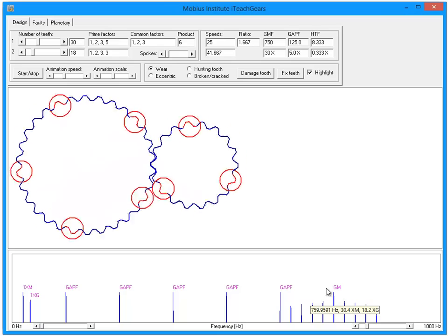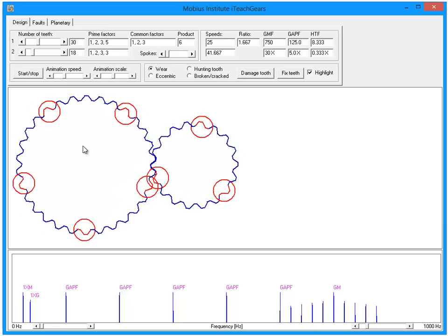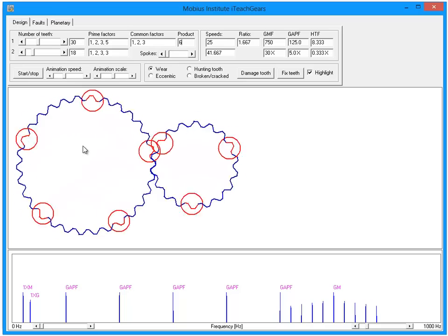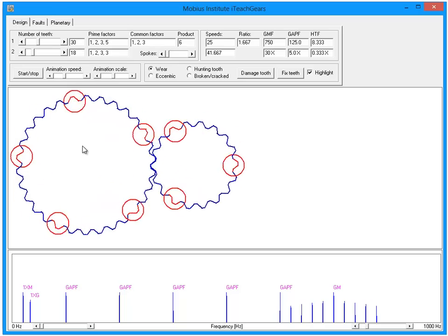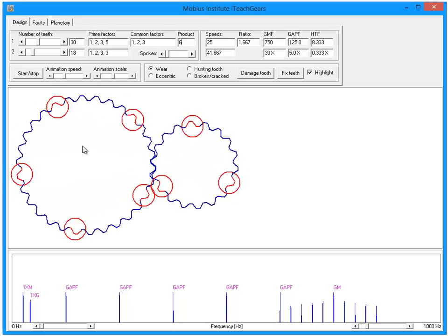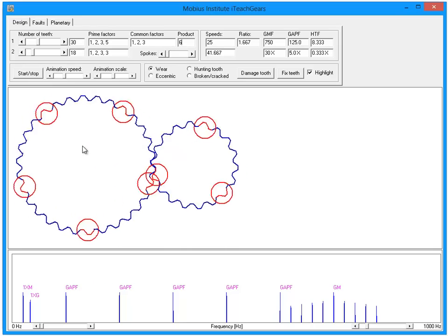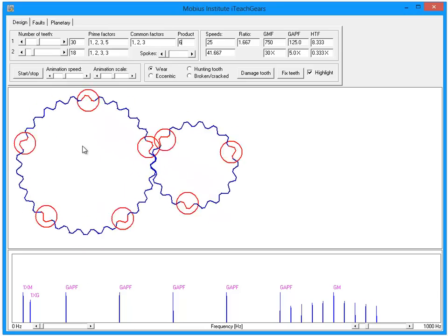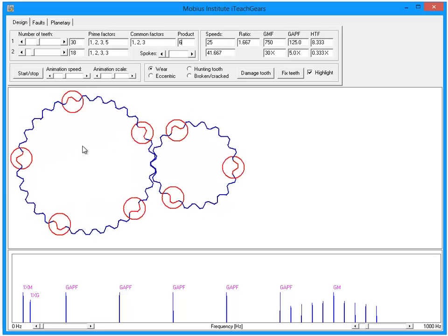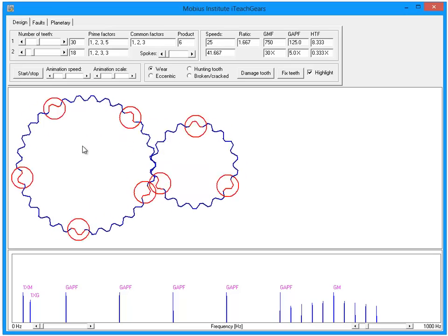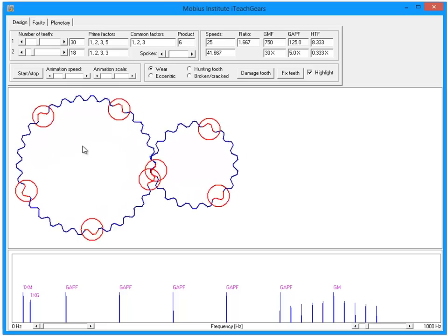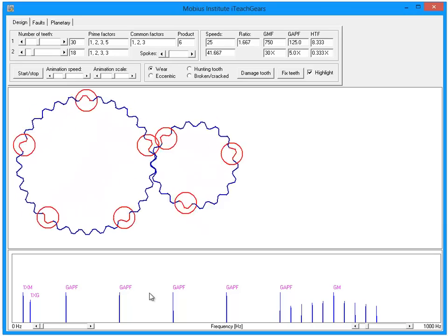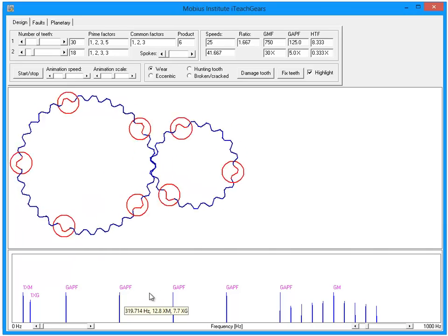And if you imagine taking this gear out of the gearbox, suspending it on some sort of cord and hitting it with a hammer, it's going to ring. It is a metal object. Now, when it's in the gearbox, even though it's mating with the other gears, it's on a shaft which is supported by bearings and so on, it still has a natural frequency. It may be different because the stiffness is changed and so on because of the configuration, but it still has a natural frequency, and therefore we have the potential to see additional peaks in the spectrum related to that natural frequency.